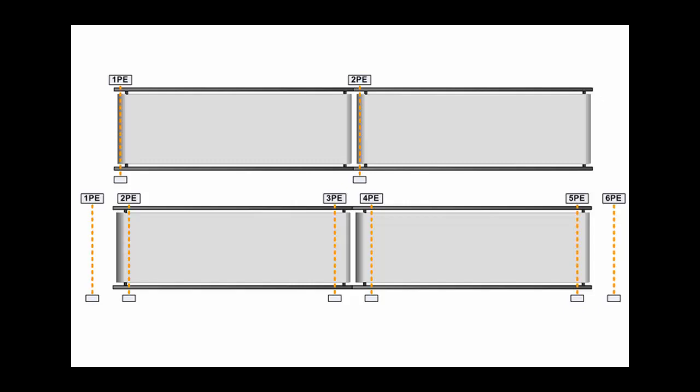Which pair would you think is the easiest for which to write a controller program? The upper pair with 2 photo eyes or the bottom pair with 6 photo eyes? Well, 6. The bottom pair, the lower pair. Why? Because you have more events to work with.